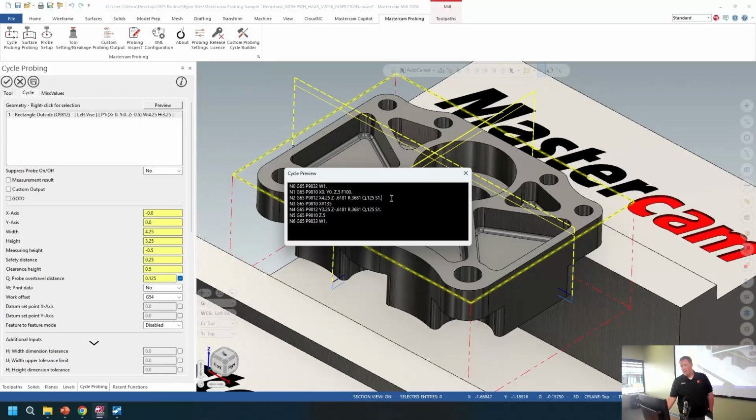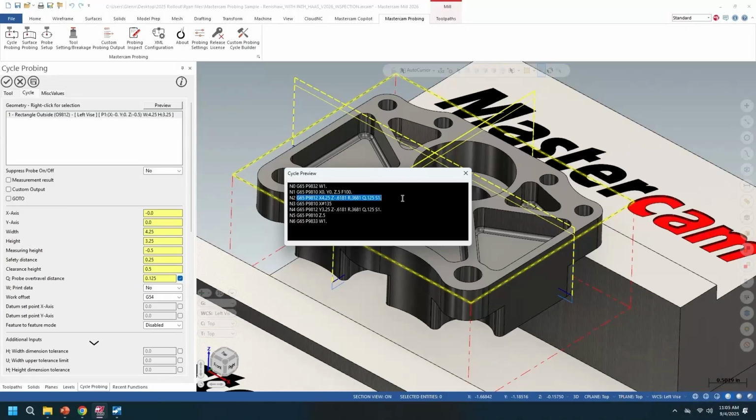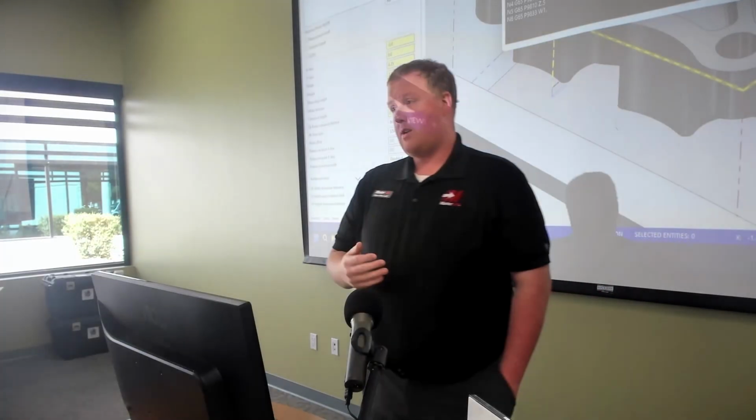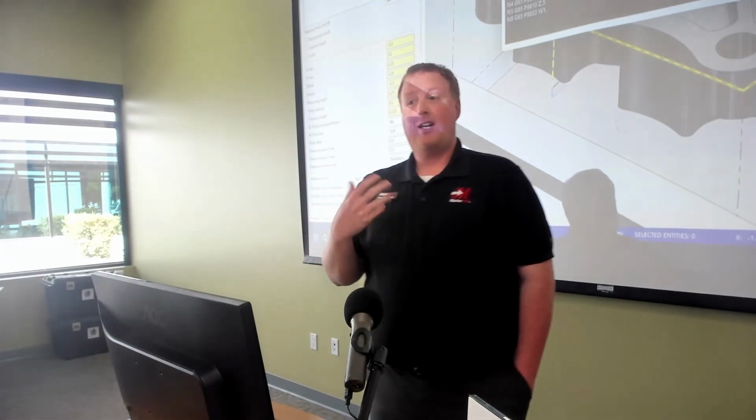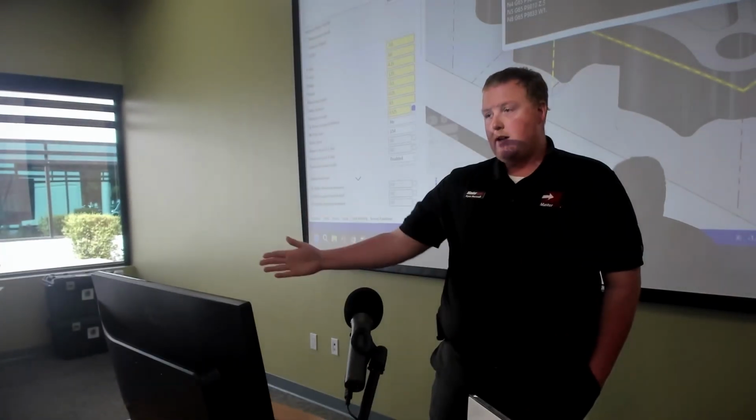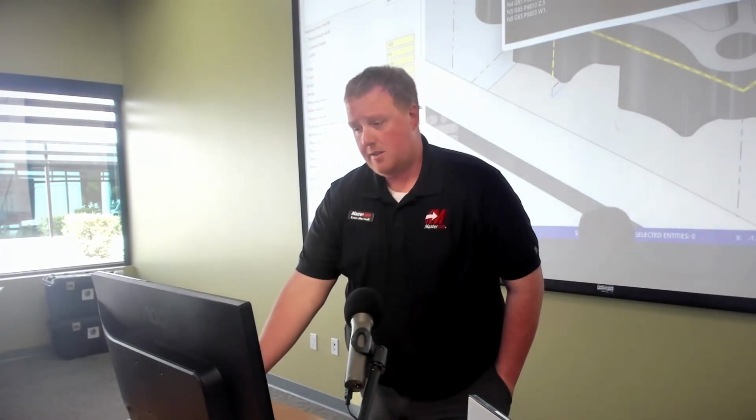But being that we are referencing, in this case, the standard Renishaw macros, right? One of my biggest things I leverage in my trainings is going to be the Renishaw Inspection Plus manual, just because that's where you can actually see where the variables are being written into and why we're referencing, like I said, a #143, what is a Q, what is a 9814, and we can make clear understandings as far as what that's doing.